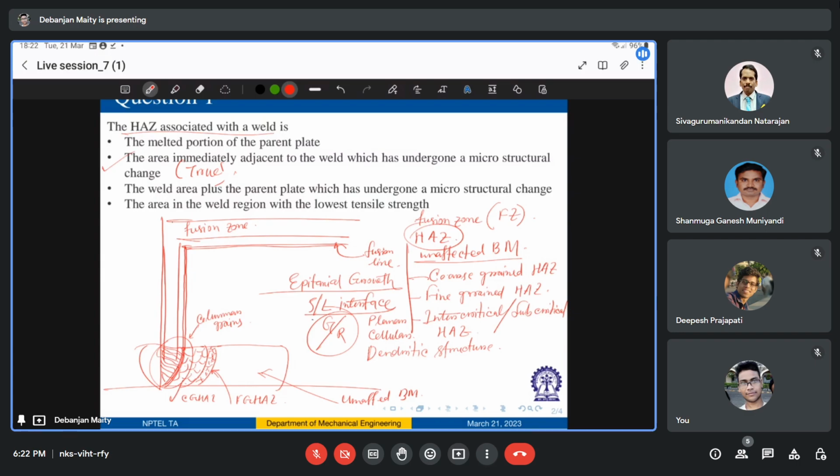So to improve the mechanical behavior and hot cracking resistance of weld metal, there have been a lot of efforts to understand the weld microstructure and to find different approaches. There are some approaches of alloying also which can make a refined grain structure. As I have already discussed, refined grain structure is very much suitable for higher weld strength, right?